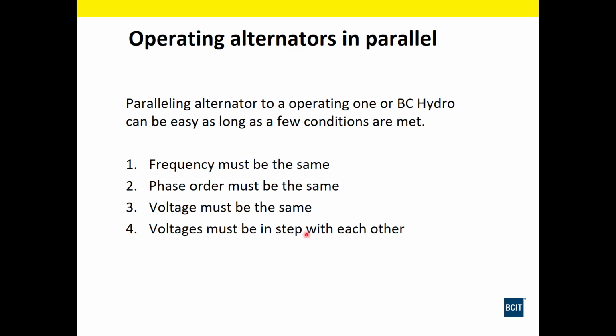They run best when they're close to fully loaded, with better power factor. Everything's more efficient at those higher end designed regions. So if you want to parallel an alternator, because let's say your load is inconsistent over the week, so sometimes you need more power added to your system.